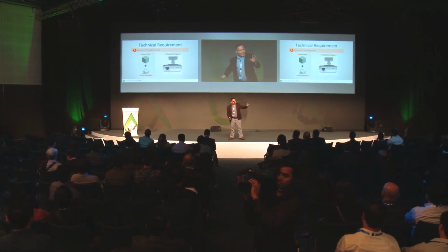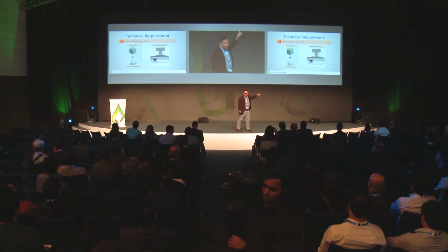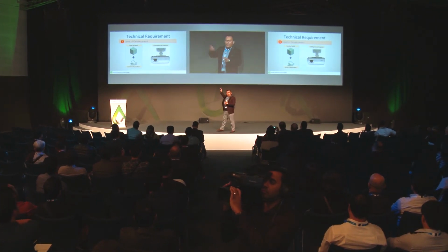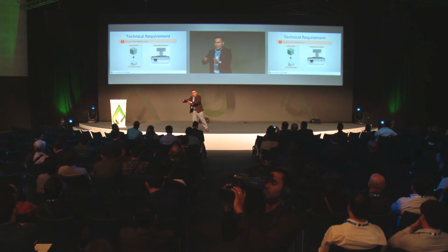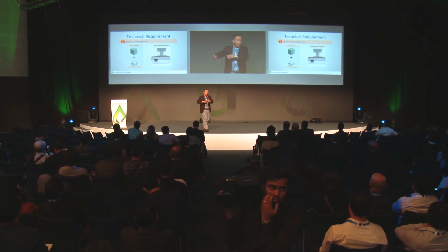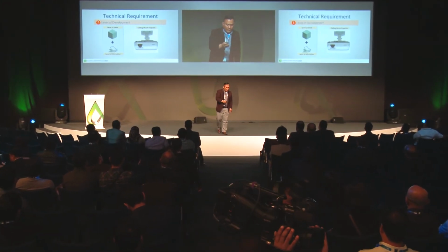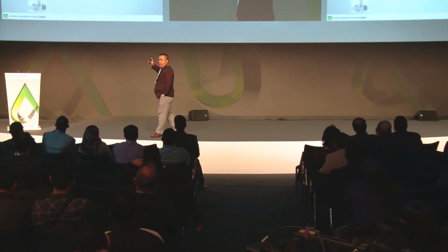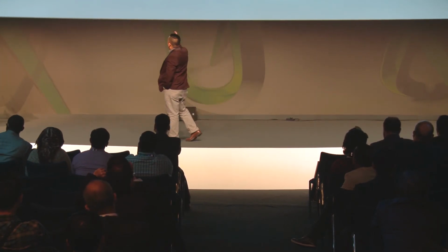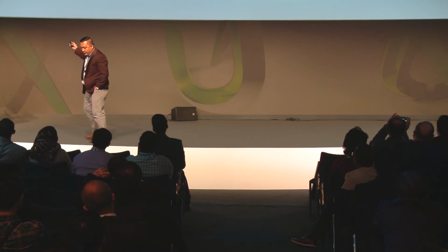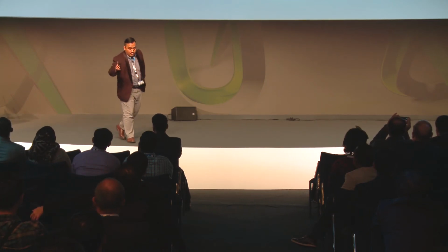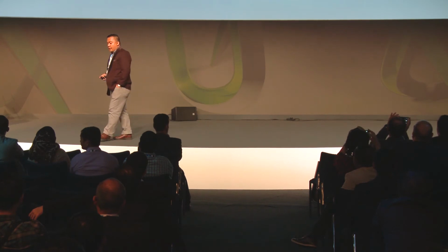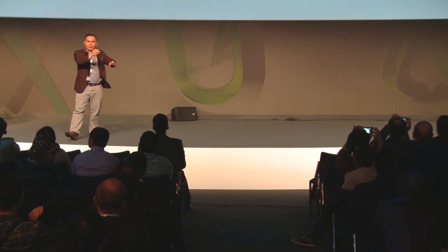So, as an example, let's take a look at this ceiling-mounted projector. How does this object or element progress through the project phases when you apply the concept of level of development? Let's say, for example, at the concept design, the ceiling-mounted projector is represented in terms of level of detail as 2D, like AutoCAD, you have 2D details. And then you have the basic information like name, type, classification. This classification is actually the OmniClass classification system, and then the location. So for the concept design, we have a 2D representation.